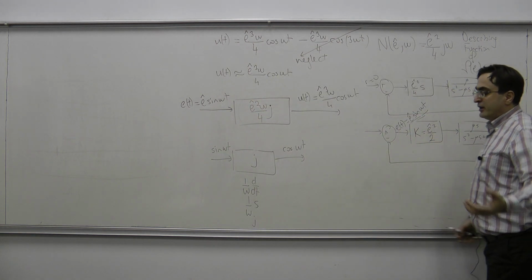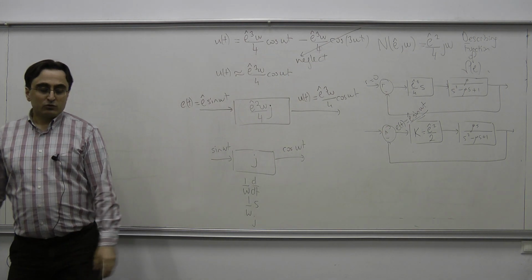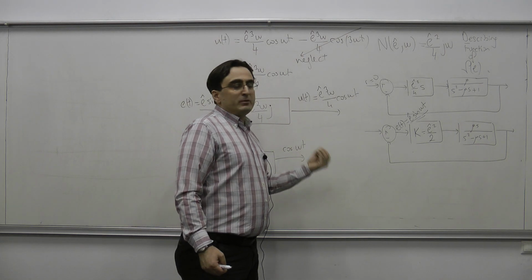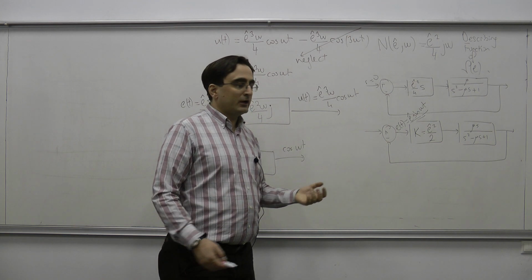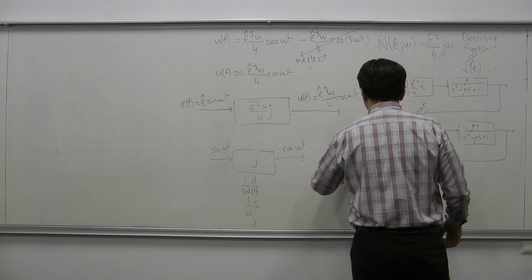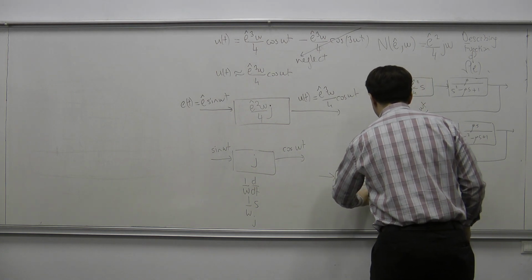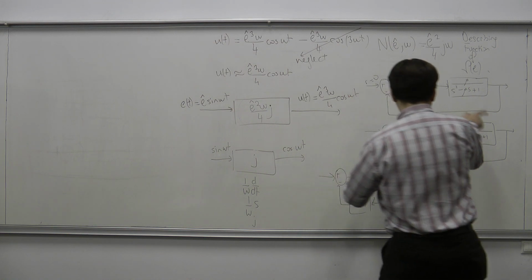So if you consider Laplace domain, what do we need? So sustained oscillations in Laplace domain would mean something about closed loop poles of a quasi-linear system, okay? So remember, if you have a linear system in this form, G of s, H of s, which is what we have here.